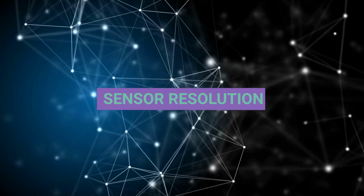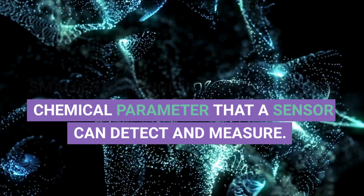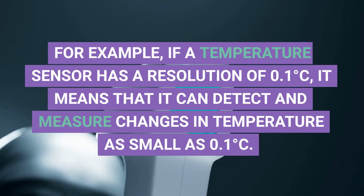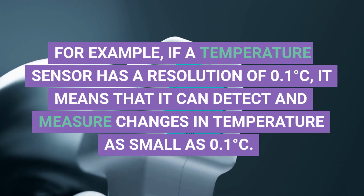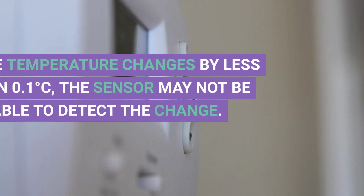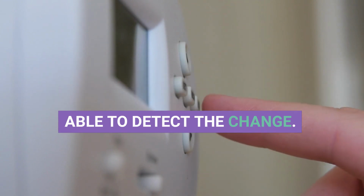7. Noise. Noise is the unwanted signals that may interfere with the signal produced by the sensor, leading to inaccurate measurements. Sensor resolution. Sensor resolution refers to the smallest change in the physical or chemical parameter that a sensor can detect and measure. It is usually expressed in units of the measured parameter. For example, if a temperature sensor has a resolution of 0.1 degrees Celsius, it means that it can detect and measure changes in temperature as small as 0.1 degrees Celsius. If the temperature changes by less than 0.1 degrees Celsius, the sensor may not be able to detect the change.